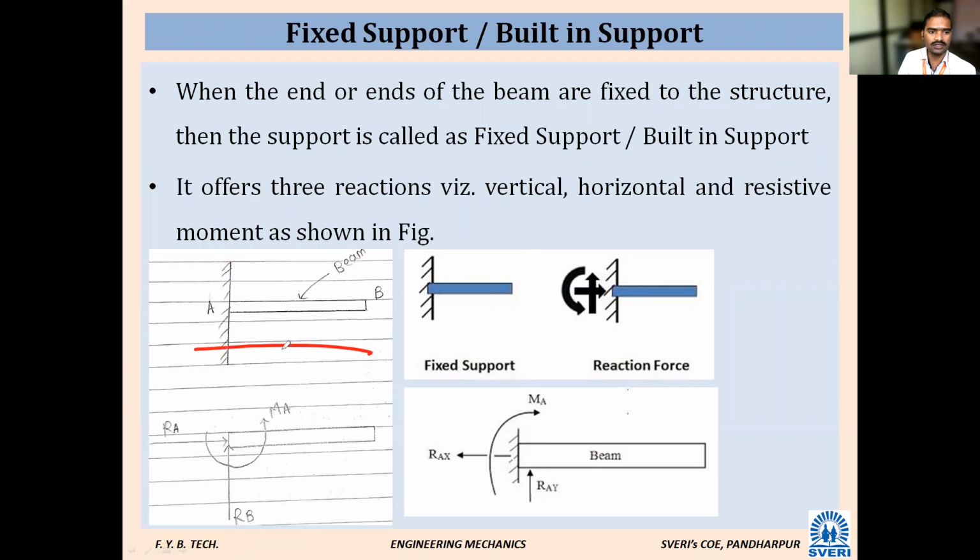So this is the beam and this is the support. Okay, support A is nothing but this point here, and B is this point. Then at support A, what are the reactions? One is horizontal. In this problem he has taken RA, but you have to take HA.